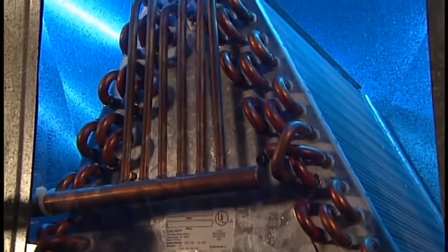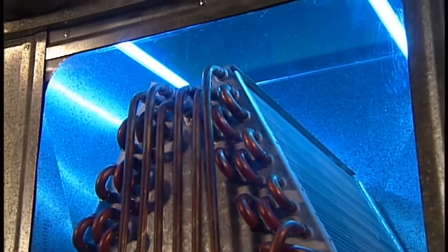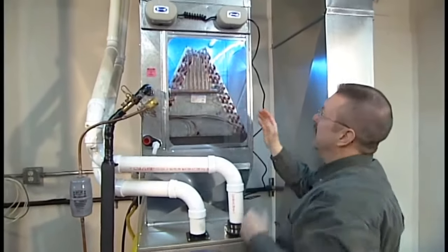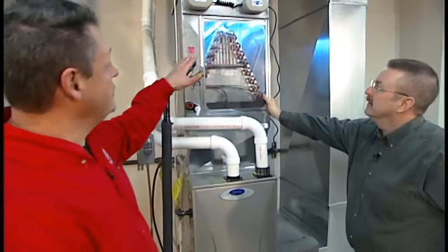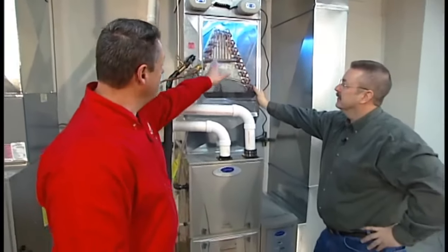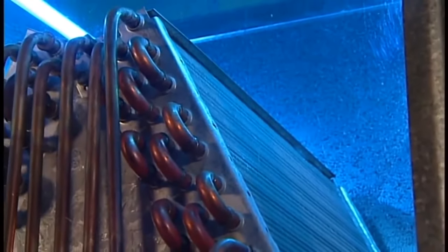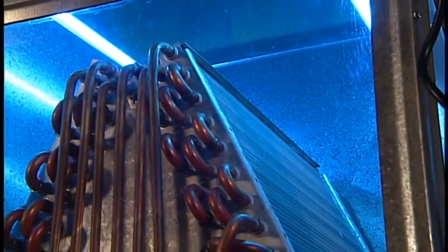The things I love about visiting your training facility. You get to see where you normally don't. And by that I mean, here's a plenum, you get to see the A-coil for the air conditioning system. And I also notice a couple blue lights up there. Yeah, the blue lights, those are actually UV lights that radiate onto the coil and the condensate pan to kill microbes that can grow on there, which does two things: keeps it cleaner, higher efficiency.